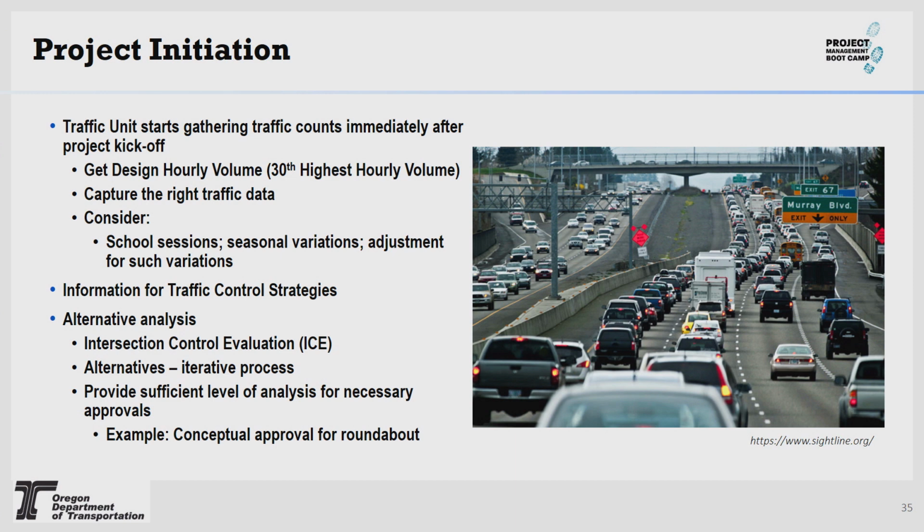In the project initiation phase, we need to start getting data, and we would like to get it early enough so we can start the analysis. We need to capture the traffic data in the right window because we need to capture the 30th highest hourly volume, what we call the design hourly volume.